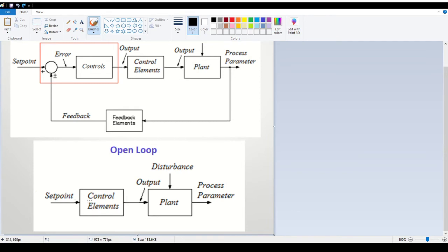All right, right now I'm doing closed loop control. So when I do closed loop control, the set point is set to 5, but it's comparing it to the previous value, and it's doing proportional control and adding gain in here and amplifying it. And so when we do that, we're actually getting some overshoot. Okay, so that's what we're seeing there. But the yellow is what we're feeding the system.